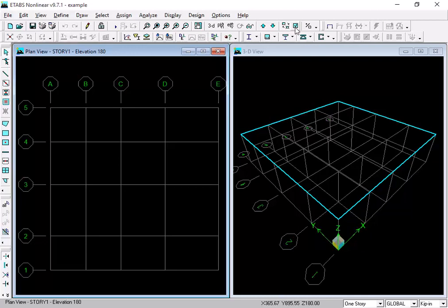That set building view options, or set building view limits options, I think, directly takes you to that panel. So you don't have to go to the view menu. It's a direct shortcut.